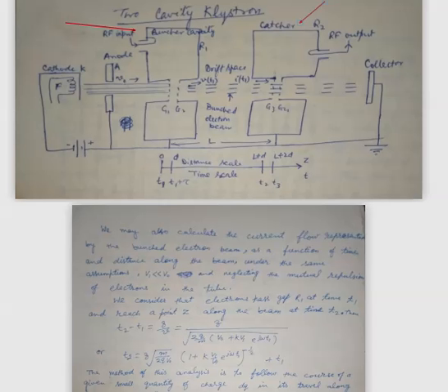From the electron gun, the electrons are emitted, and after that they are accelerated by the DC potential applied between cathode and anode, and we are assuming that all the electrons emitted from the surface of the cathode, after acceleration, have the uniform velocity v0 before reaching the grids of the buncher cavity. The first cavity grids are named as G1 and G2,